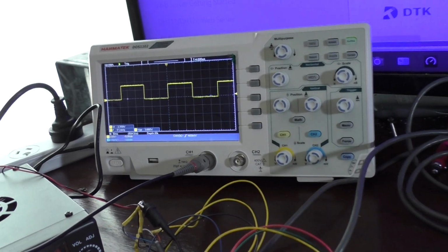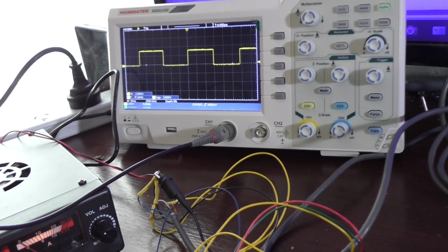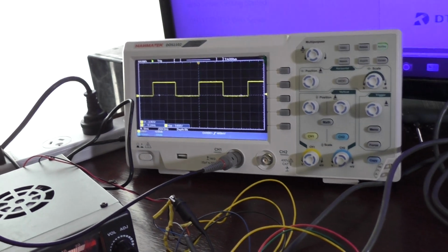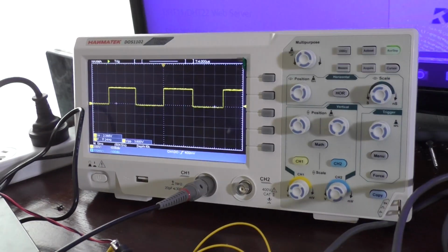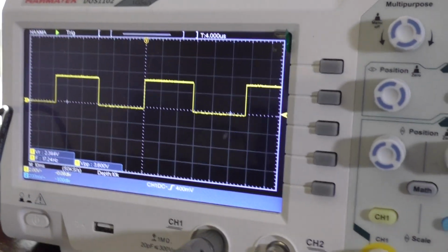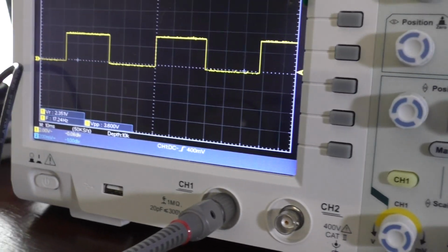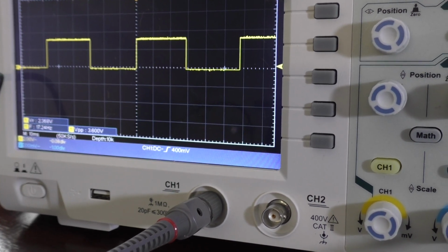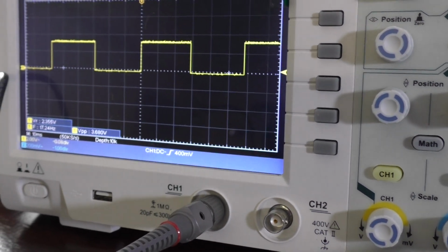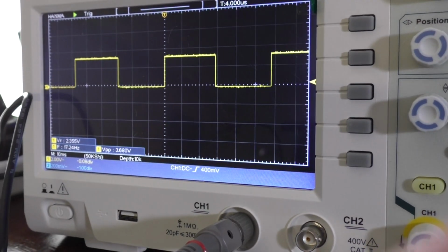One of the disadvantages of this is that it will reduce the sampling rate, the loop speed, as it's doing all this display stuff. Sending out stuff to the display obviously slows it down, goes without saying, and it goes down to a sampling rate of about, measuring it here on the scope, 34 Hertz. So that means you get a bandwidth up to 17 Hertz.